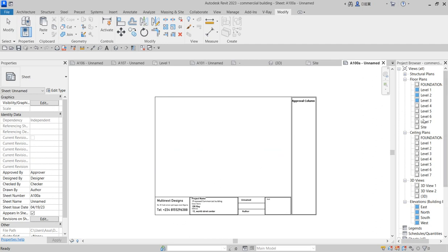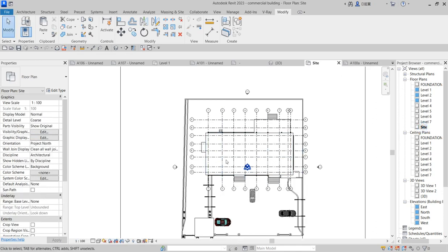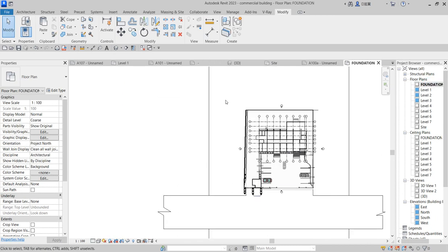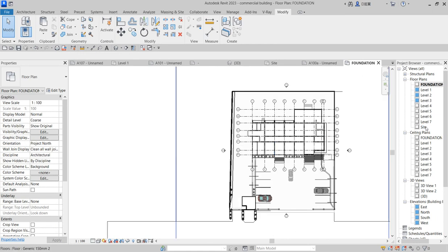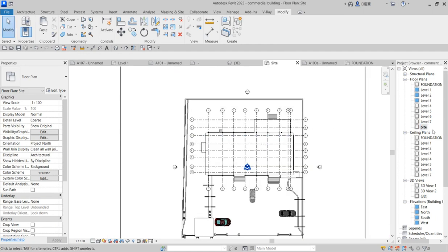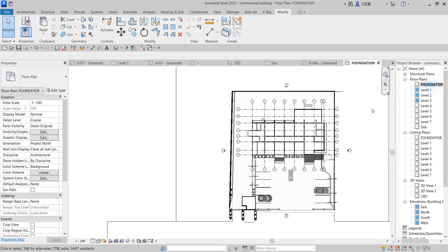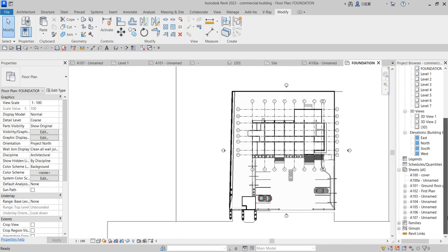Now if I want to do a site plan, I don't encourage people to pick the site from this, because if you pick this particular site, it's taken from the roof edge. It's the proper way to do, but that is not the best way for me. That is why I always create a foundation. I want the foundation already related to the ground level of everything I want to do. Because if your house is cantilever, this is going to be the cantilever also. But make sure that you use foundation to create your site plan, so every other thing you want to add there is made possible.